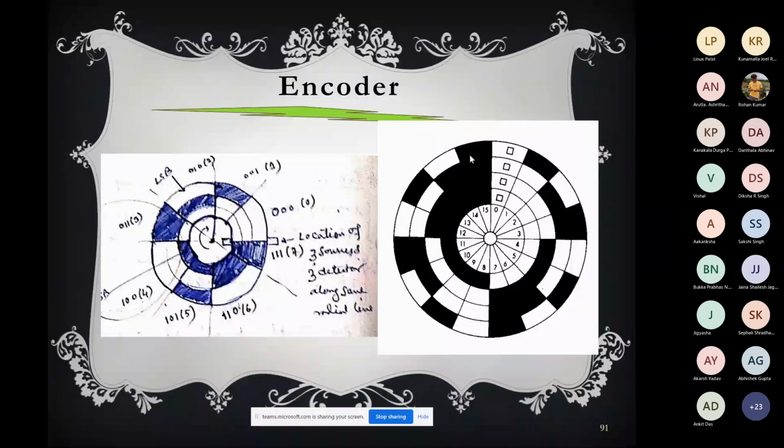Then you apply a Schmitt trigger. If you apply a Schmitt trigger on this sinusoidal or changing signal, you will get a square wave. Now you apply a counter, so you count the number of peaks of the square wave and the time span. You divide the number of peaks by the time span, and you will get the velocity. You know how to calculate the velocity very well, so this can be used as a velocity sensor.